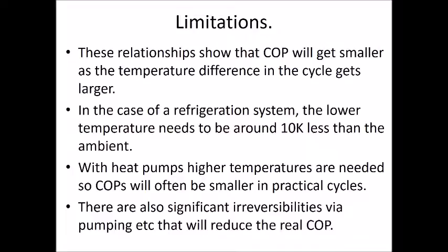Now the problem starts to come in with heat pumps, in that the heat pump is going to be driven from the other side, isn't it? We're going to have a set point temperature that we want. So if the outside environment is very, very cold and I'm upgrading heat from one source to another internally, I'm upgrading very cold heat energy to much warmer heat energy, my coefficient of performance will be hopeless. It will be really bad. I could be trying to drive over a 40 or 50 Kelvin delta T.